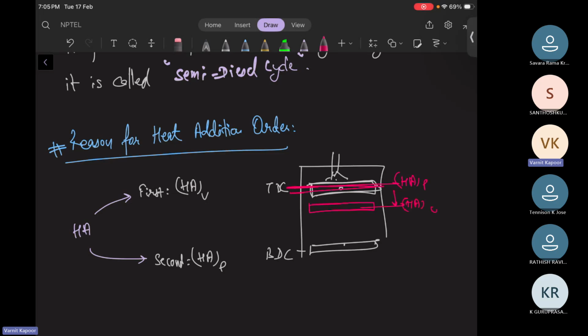No. It is impossible to stop this piston when it is moving from TDC to BDC during the power stroke, running at such high speeds, to add heat at constant volume at that instant. You never know how fast the piston is going down, but we know the velocity of the piston is zero at the dead centers, compared to the middle, where we don't know the velocities. So one practical way to say it is that it is impossible to stop the piston midway. We cannot do heat addition at constant pressure first and then constant volume. It always has to be volume first, then pressure.